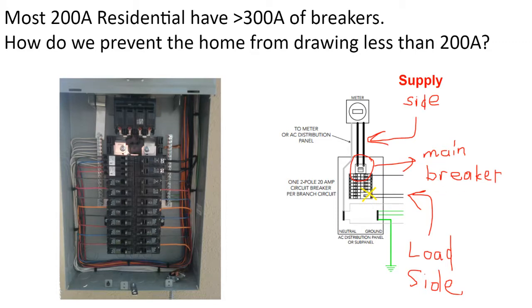Obviously, this is not the case for solar, and National Electric Code allows an exception. When the solar breaker is located at the opposite end of the bus bar from the main breaker, rather than inserted somewhere in the middle, so if the main breaker is at the top of the panel and the load side solar breaker is located at the bottom of the panel, an additional 20% amperage allowance can supply the electric service panel. In other words, a 200 amp electric service panel can be fed with 240 amps of power divided between the utility main breaker and the solar array.